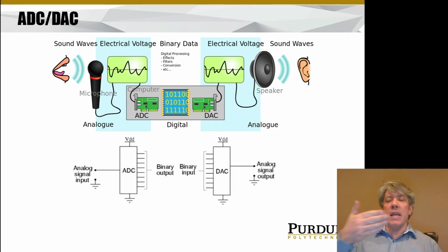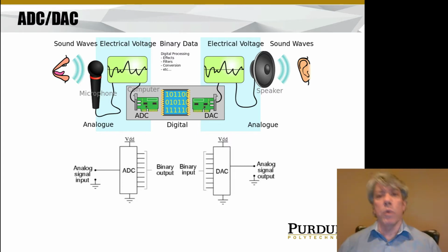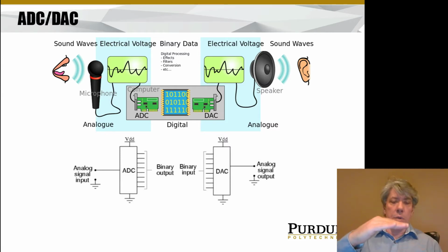And what that piece does is as pressure waves hit it from your voice, it literally moves back and forth. So on axis from my voice, it would be moving back and forth towards and away from me. And if you were to plot that in accordance with the way the microphone is oriented here, the diaphragm would be moving up and down basically in response to the pressure waves that it is experiencing.